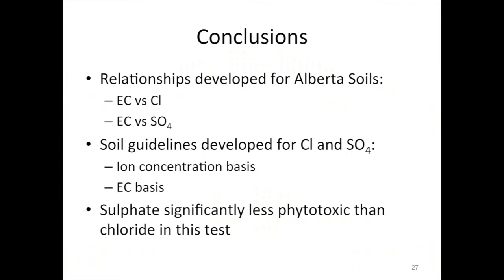So in conclusion, this project developed relationships for Alberta soils between EC and the chloride ion concentration and EC and the sulphate ion concentration. We developed soil quality guidelines for chloride and sulphate, and just to be clear, these are guidelines based on the SSD approach, the species sensitivity distribution, which is our current method of developing guidelines, but is not consistent with the way that the current EC guidelines are developed.